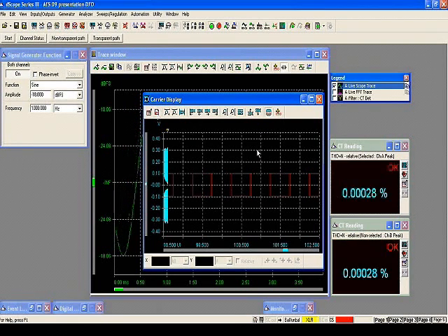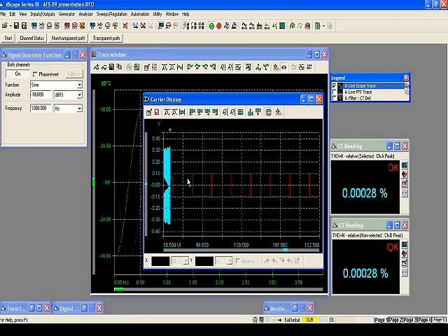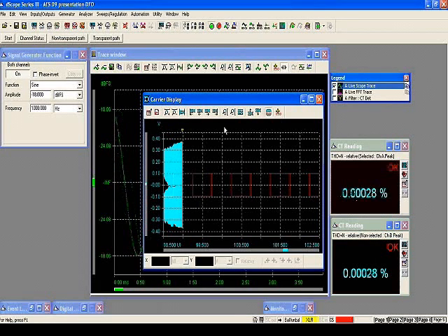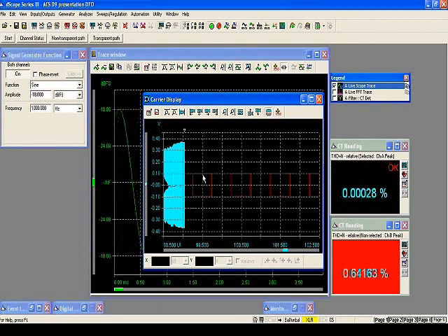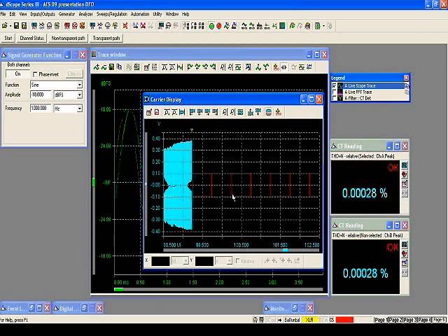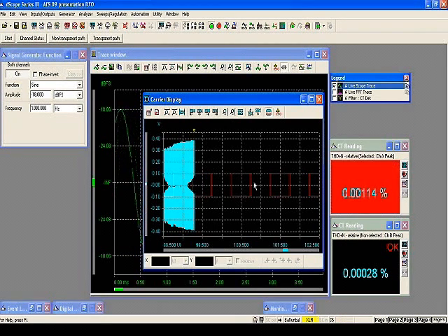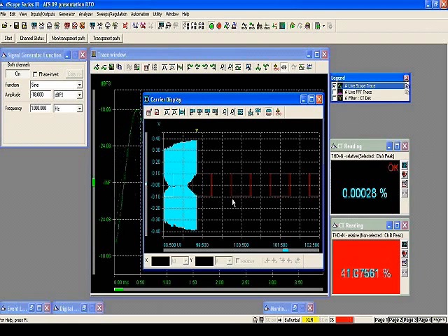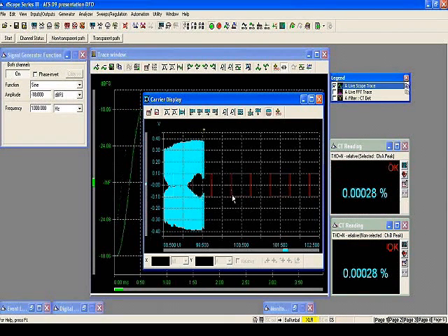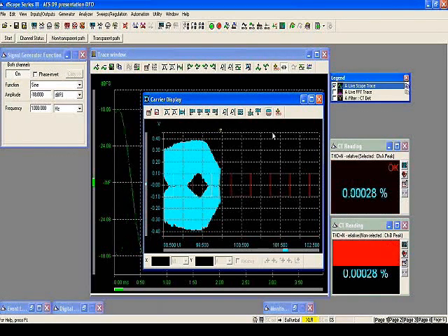This is a measurement that's made using a high persistent wide bandwidth storage scope, and the D-scope emulates that. We'll get into depth in this later, but you can see these red boxes that appear, and those red boxes are the AES limits for receiver acceptance. And you can see that our eye pattern is walking on those boxes. So that tells us that we've got some problems.